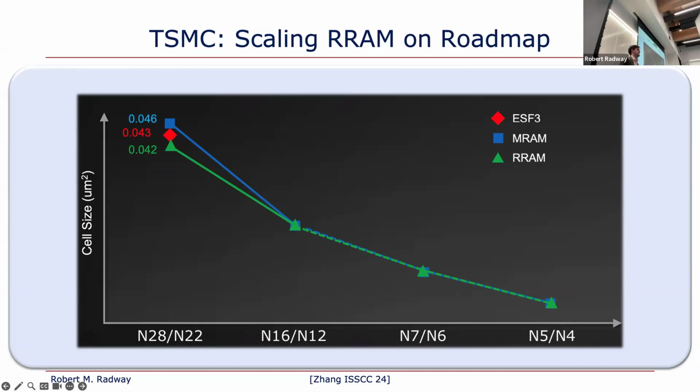Yeah, essentially, if you have a quantifiable speed up in one area of your process, how does that reflect on the overall speed up of your system? The simplest way is you're limited by the worst performing part of your system. So if we make our accelerator awesome in terms of performance and energy, the other stuff becomes the worst performing parts, and we're limited by their performance.